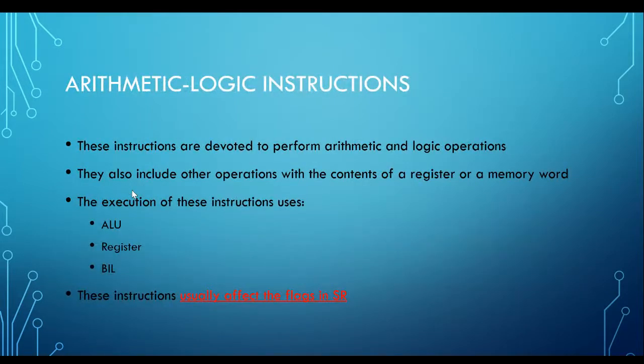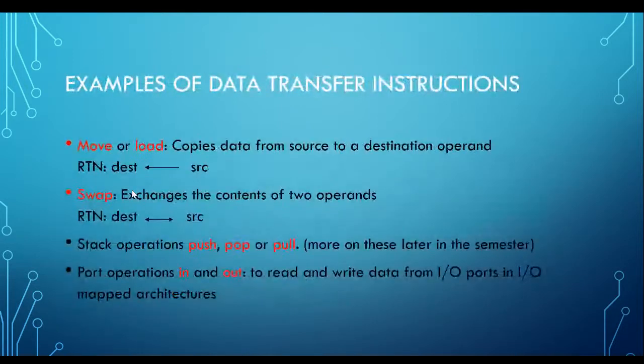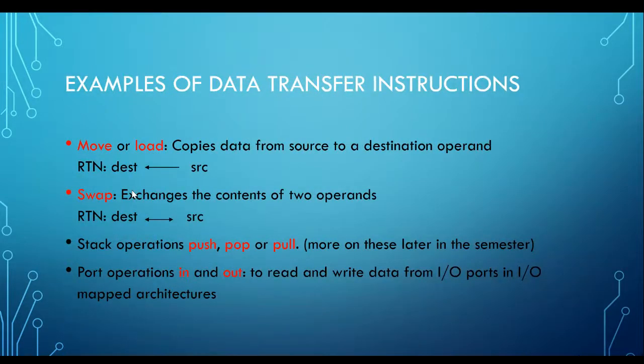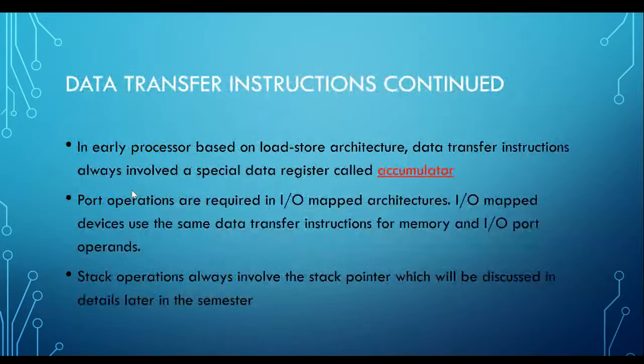The execution of this instruction uses the ALU, registers, and bus interface logic. So your ALU is also involved. This instruction usually affects the flags in the SR. This one is the arithmetic logic instruction. What are arithmetic logic instructions? Plus, minus, divide, things like that. The data transfer only involves moving information from one register to another.